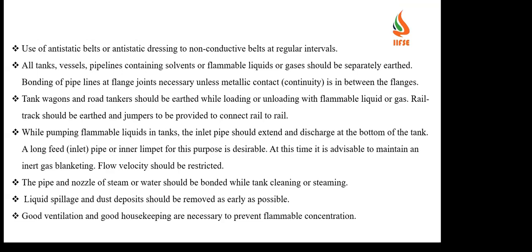Then use of anti-static belts and also anti-static dressing to non-conductive belts at regular intervals. And all tanks, vessels, and pipelines containing solvents or flammable liquids or gases should be separately earthed. So whatever tanks you are using for storage, separate earthing should be provided. And bonding of pipelines at flange joints is necessary unless there is metallic contact connectivity between the flanges. Sometimes we have leather or Teflon kind of gaskets. There will be a chance of accumulation of charge.